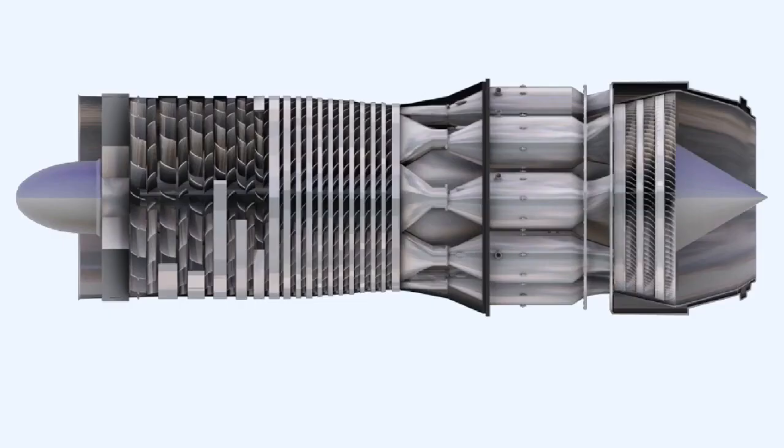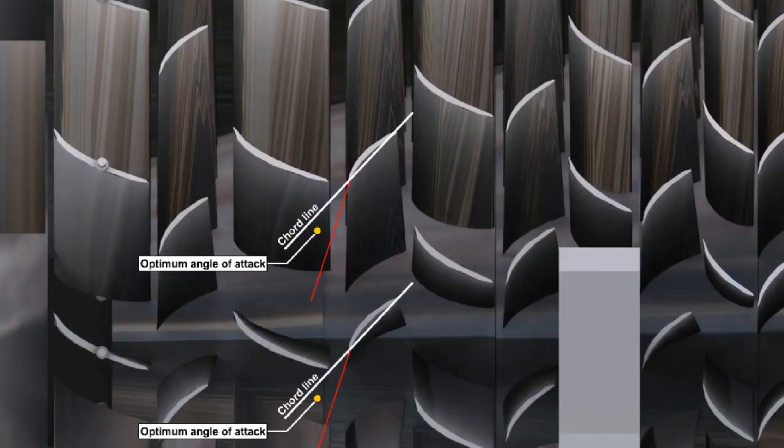The design of early axial flow engines was developed by adding more compressor stages on one shaft to obtain higher and higher compression ratios. Unfortunately, having many compressor stages on one shaft makes it increasingly difficult to retain the engine's operational flexibility in terms of being able to operate it over a reasonable RPM range. Compressor blade angles are arranged to give peak engine performance around maximum RPM, when the values of the axial velocity of the airflow and the rotational speed of the blade combine to produce a vector which is the optimum angle of attack of the airflow over the blade.